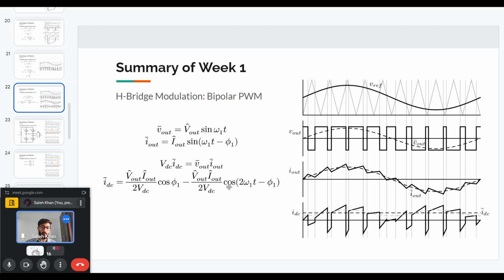But again, depending on how much capacitance you have and how much you allow the battery to supply the AC portion of the current, the battery will supply the current in that fashion. And if there is more reactive power, then we'll probably need a larger value of capacitance to handle the power oscillations. So is that clear or do you need more clarification?